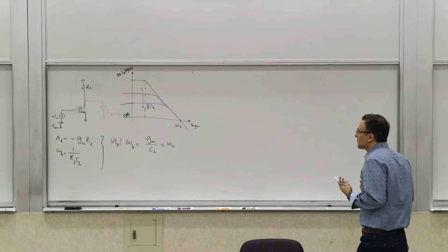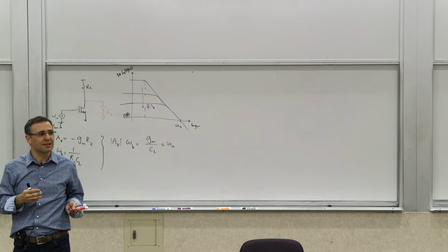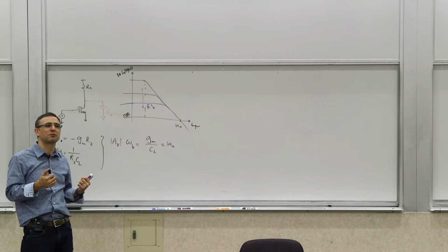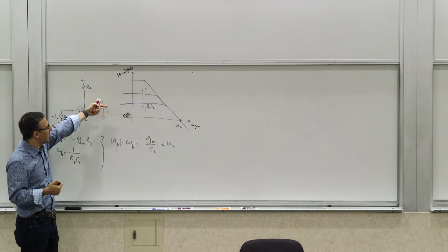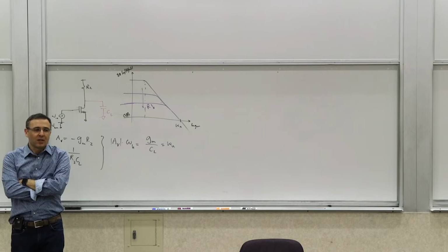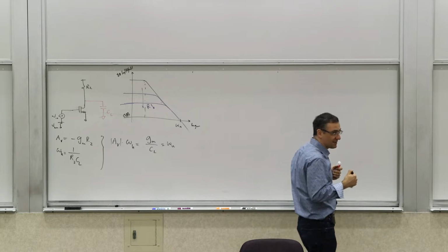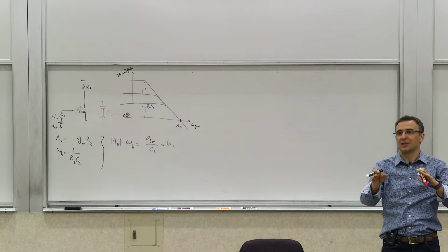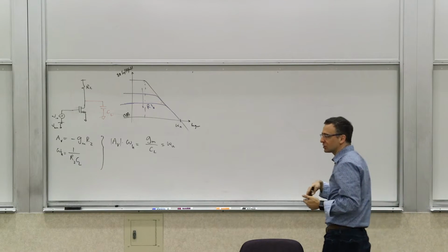So there appears to be the gain bandwidth product, at least in this simple example, to be fixed. Now, if you write more elaborate examples, you will see that it's not exactly fixed, but it's kind of changing more or less, not a lot, if you calculate this product. And we'll see that there are different ways of achieving this. So what you're doing is, as you're lowering R, you're throwing away the gain here, and you're recovering it here, right? So there's this notion of gain bandwidth product being a constant in general. Now, this is not exactly so, let me tell you what the general conception is. There are people who say, oh, the gain bandwidth product is a constant, or more or less constant, right?